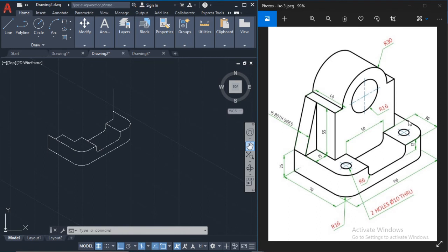If this was a rectangle, if there was no curve here, this would be a rectangle that would be 30 by 30, and the circles are dead center in that rectangle. How do I know that? You're not given the location of the circles, but you can look at the drawing and see that if you continue the center line, it will meet up perfectly with this line here.